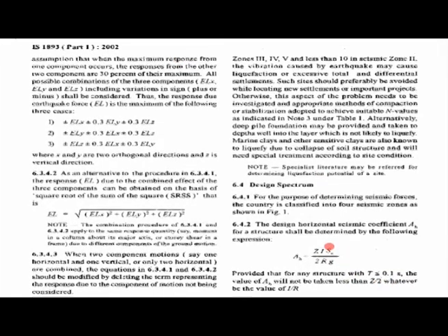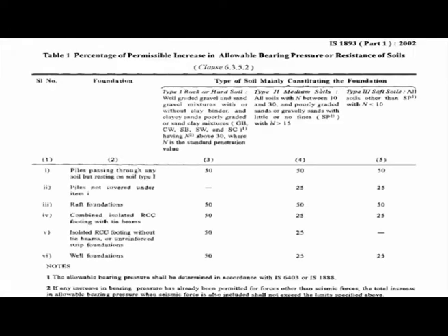Next part we have I. What is I? I means importance factor. So how important the building is, for example any assembly building, any heritage building, those important buildings. We get the importance factor depending upon the functional use of the structure, characterized by hierarchical consequences of its failure, post-earthquake functional needs, historical value or economic importance. So we shall get the value of the importance factor here.